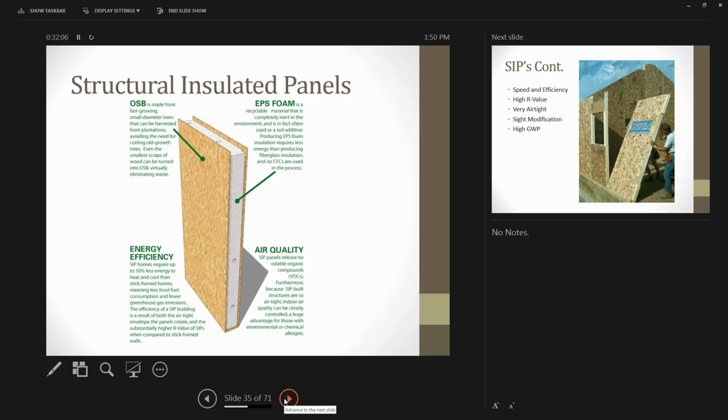The way that these are made, you've got an expanded polystyrene foam core, and on both sides of it are laminated skins of OSB, primarily OSB. Yeah. So there is no thermal bridging from inside to out. They're put together with a spline system rather than 2 by 4s, and if they're sealed up properly, usually about 50% better when it comes to air infiltration.